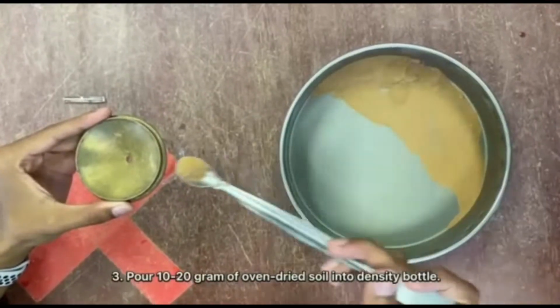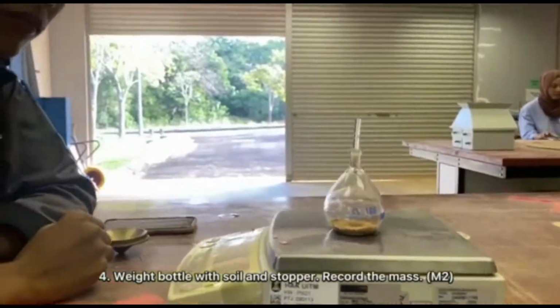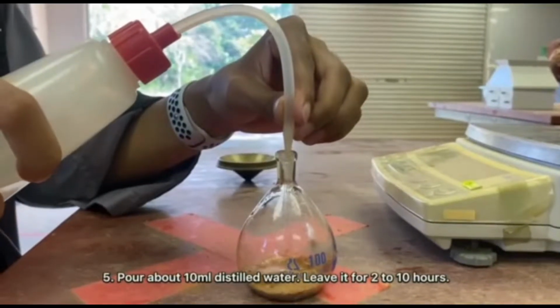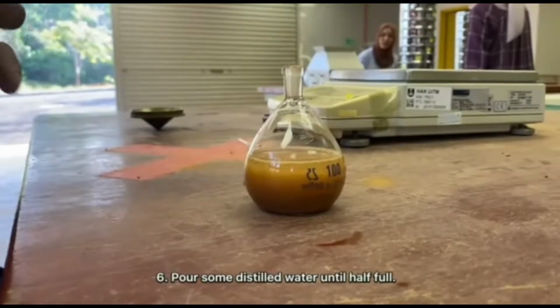Next, pour 10 to 20 grams of oven-dried soil into the density bottle. And then weigh the bottle with soil and stopper, and record the mass. Pour about 10 ml of distilled water and leave it for 2 to 10 hours. And then pour some distilled water until half full.